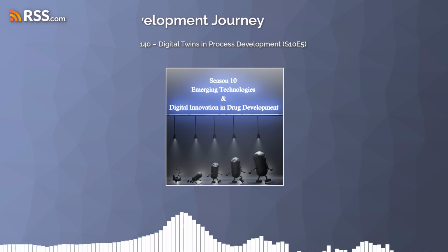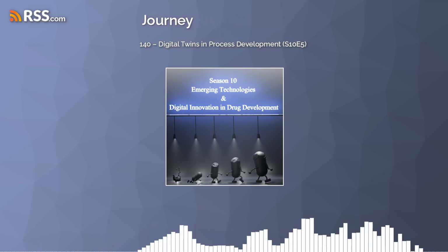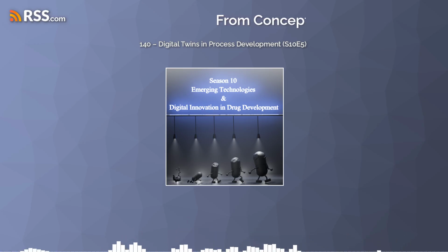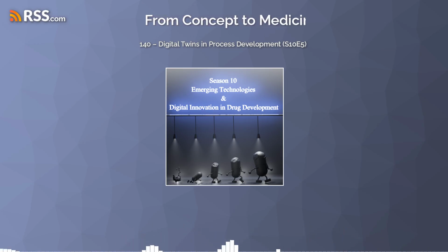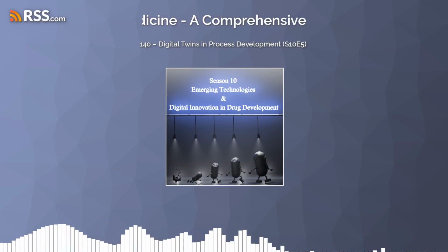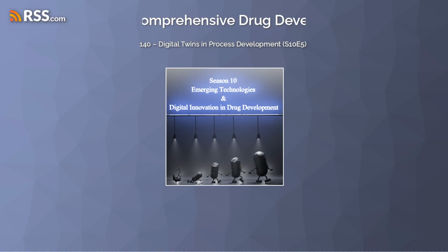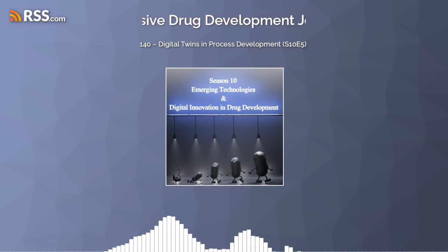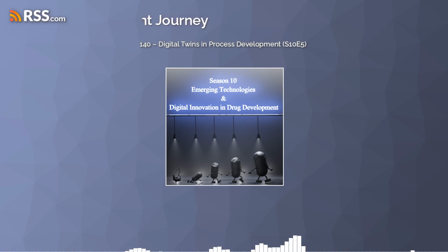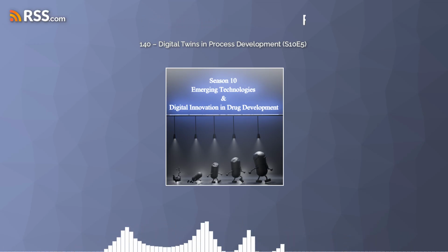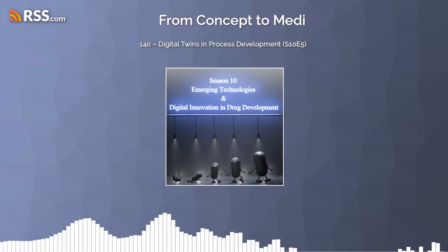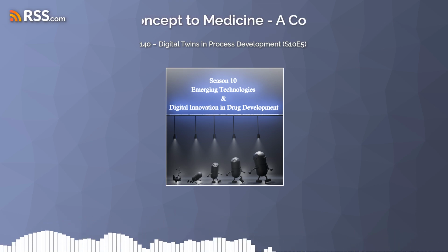Well, you can use it to model the crystallization process itself. Simulate how factors like temperature changes or the type of solvent used might influence which polymorph forms. So you could predict if you're likely to get the stable, desirable form under certain conditions. That's the idea. Predict and control it. You can simulate different scenarios to find the processing window that consistently gives you the polymorph you want and avoids the problematic ones. Okay, virtually designing the crystallization to avoid downstream surprises.